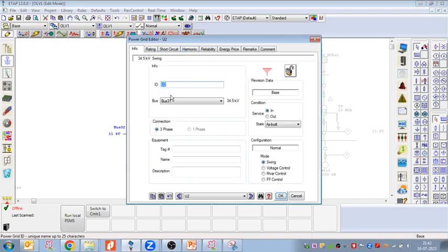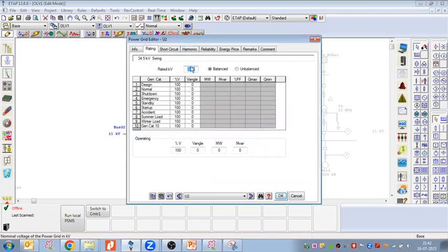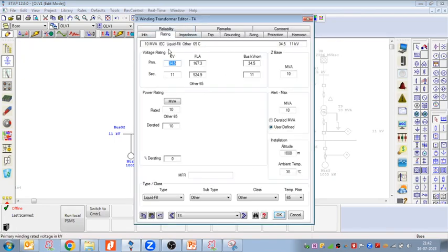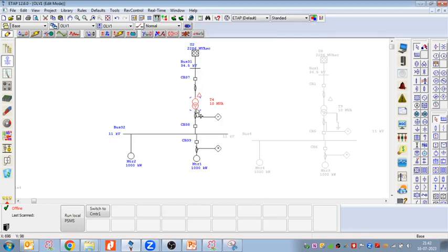Here we have a grid, and the grid is 33 kV. This grid is feeding a 33 by 11 kV transformer, and on the LV side of the transformer we have 11 kV voltage. We feed that 11 kV to an 11 kV panel board, which is further connected with different loads. And here we have the breakers, CTs, relays, all these things.